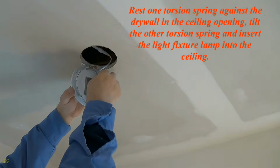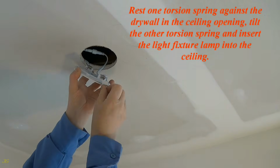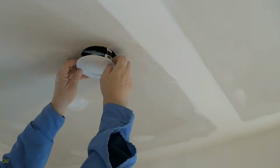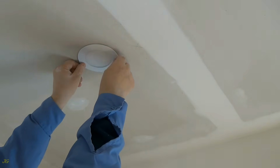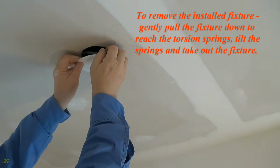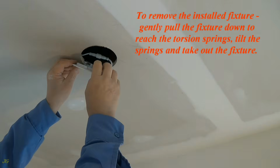Rest one torsion spring against the drywall in the ceiling opening. Tilt the other torsion spring and insert the light fixture lamp into the ceiling. To remove the installed fixture, gently pull the fixture down to reach the torsion springs. Tilt the springs and take out the fixture.